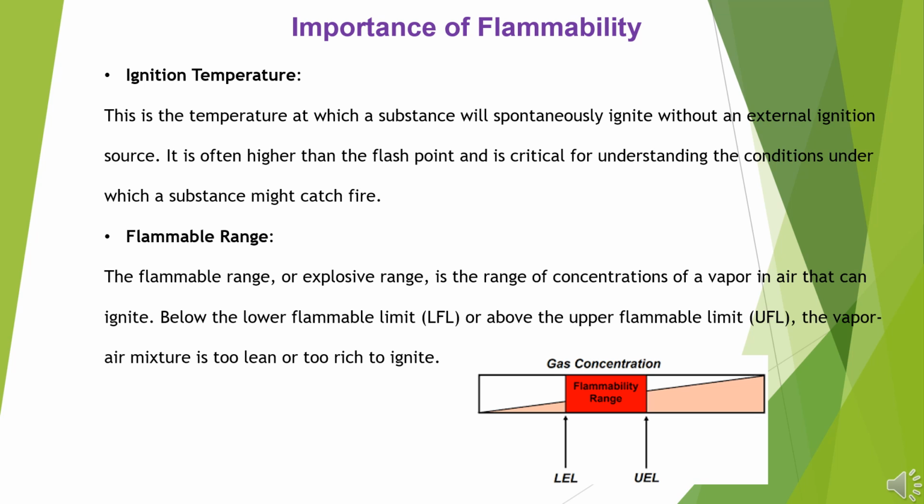Flammable range. The flammable range, or explosive range, is the range of concentrations of a vapor in air that can ignite. Below the lower flammable limit, LFL, or above the upper flammable limit, UFL, the vapor-air mixture is too lean or too rich to ignite.